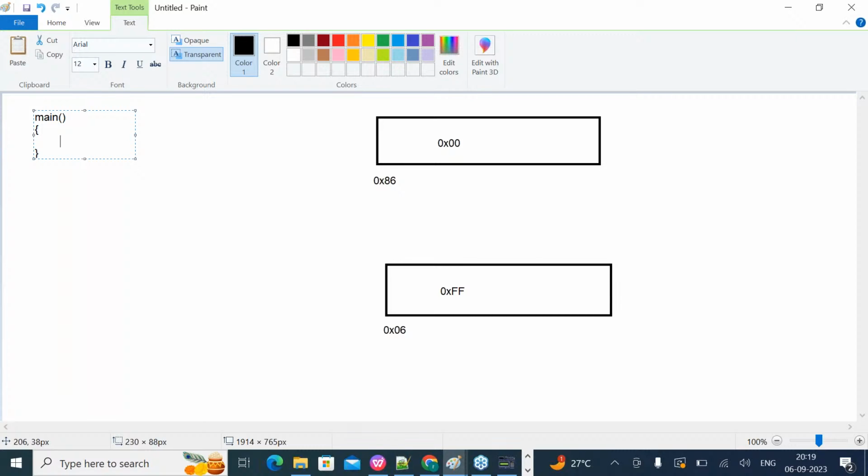Very nice. But if you see here, the maximum data you can write in this register is just 8 bits. So let me take a pointer of type unsigned char, star PTR, or let me give the name of the first pointer as TRISB, just for clear understanding. To this pointer, let's assign the address 0x86, which we got from the datasheet.